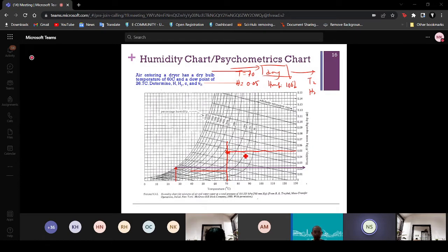So which one is near? You have the upper one and the lower one, adiabatic saturation curve lines. So you choose the upper one. Take your ruler. Trace that line first, then bring it down a little. So your ruler is there. Maintain the same gradient here. And then draw a parallel line until 100%.